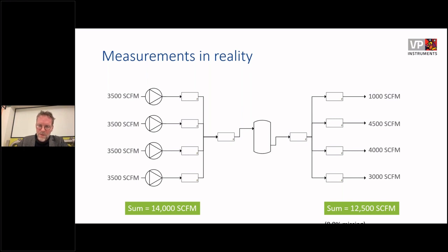But if you look at the longer run and you still see this difference, it could also indicate that there are some leakages in air treatment, or there may be a drain that's open, like a timed drain, or an automatic drain that is broken and needs to be cleaned out so it closes nicely again. Or it can be one of those flow meters downstream that has an installation error causing this.